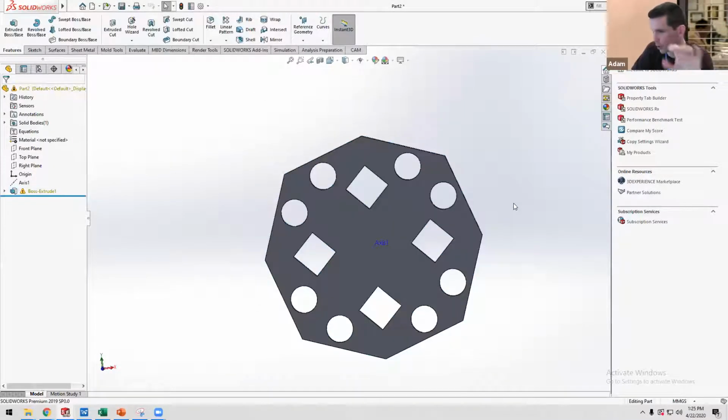From there, I would open it in Adobe Illustrator. I would make the stroke width very, very small, like 0.002 millimeter, and then I can hit File, Print, and make it go to the laser cutter from there. So that's how you generate some laser cutting files.